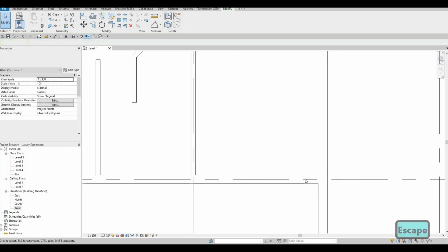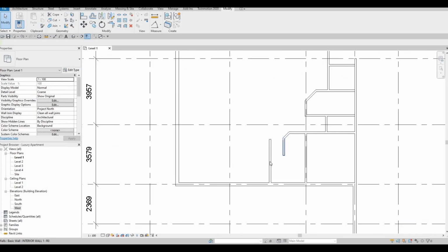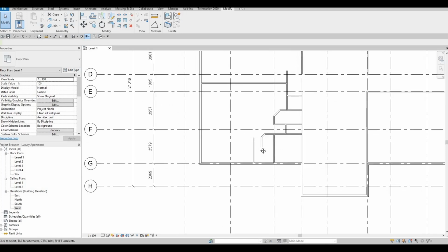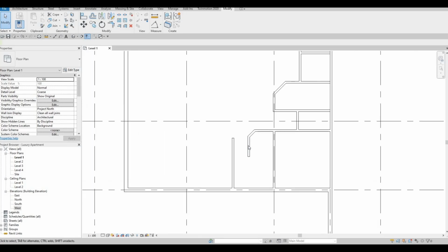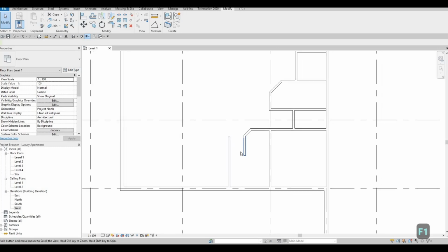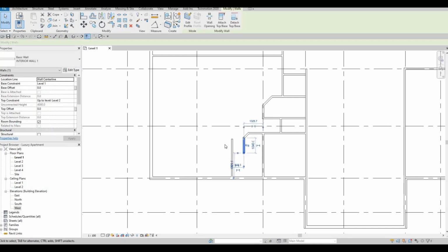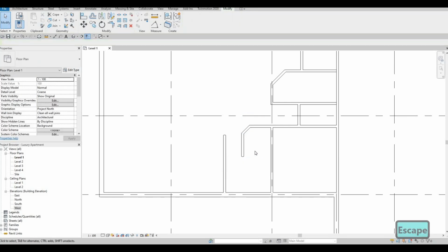So that's the only difference that I want you guys to do, because I noticed that the walls are very thick and I forgot to tell you guys to change it to 100. So that's a good example of organizing any system walls that you have, so that if you need to change one, it will change on all of them.